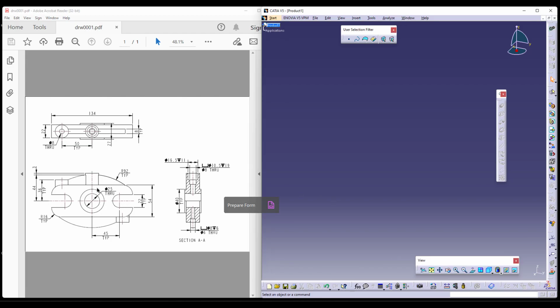Now, the reason why we understand that is we have a counterbore hole here which is located at this location, and of course a center hole which is cut at this, as well as there are two other holes, one counterbore and a very simple hole at this location, which we can understand from the top view. Now, there is also another one which is a circle which is added over here with a hole of 8 diameter. Now, considering this as the front view, this will be the top view, this will be the right view.